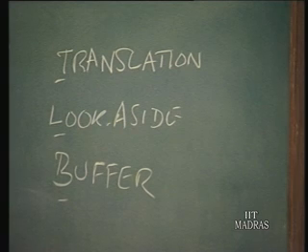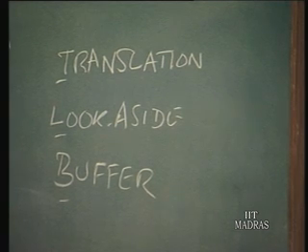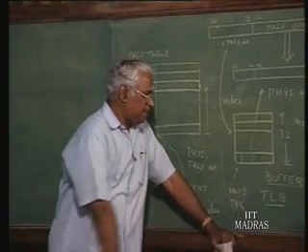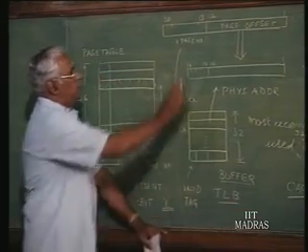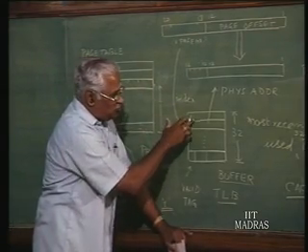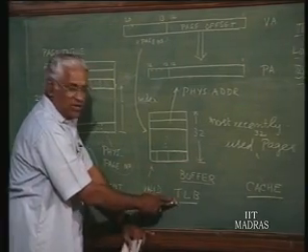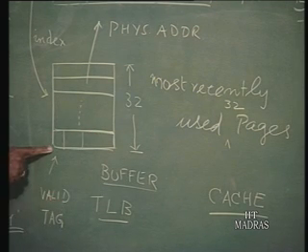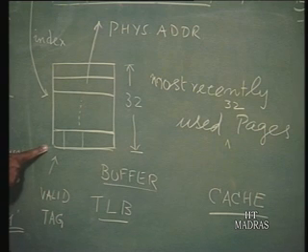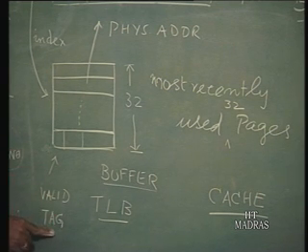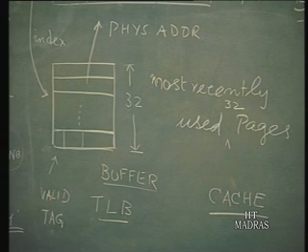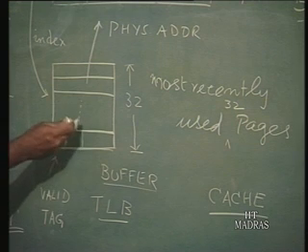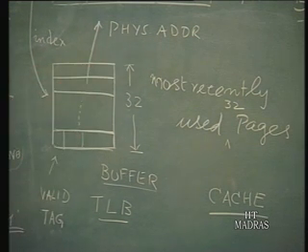Just call it TLB. Now, this particular thing is a reasoned arrangement in some of these processors. It is very much like a cache. So, the virtual page number will index into the 32 entries of the translation lookaside buffer, and the entries here, like in a cache, will indicate whether the particular entry is currently valid or not. It will also indicate which, because it is only a subset, 32 of 256, which of these is currently available here. If so, there is no more translation; it directly gives the physical address that is required. This is what you may call an architectural arrangement to speed up the whole thing.